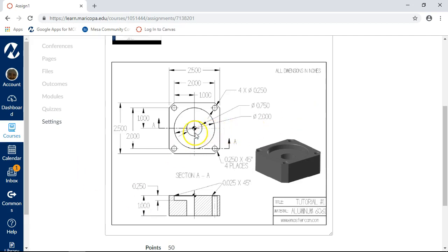All right, so I said that I'm not fond of the origin at the center. The mold making strategy, as far as I know, is to put everything at the center, and then regardless of the shape of the material, we're aligning our geometry center of that part, and then everything fits into it regardless of how square our mold base came in. All right, this isn't a mold, so I can make the case of I want to go with what's convenient, basically touching off on one of the corners.